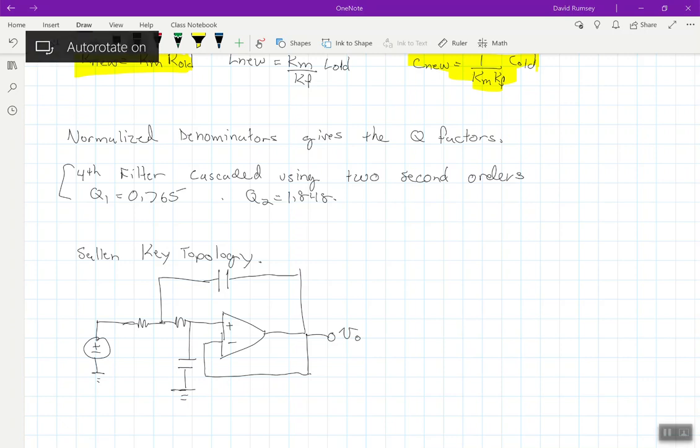And by implementing it this way, I'm going to put in component values in a second. The key thing is this has unity gain. Because right now for this first lab, we're just trying to get these to have unity gain. And we can worry about the gain in later stages. And that's typically what you want to do: you don't typically filter and gain at the same time. You do your filtering and then you might do your gain.